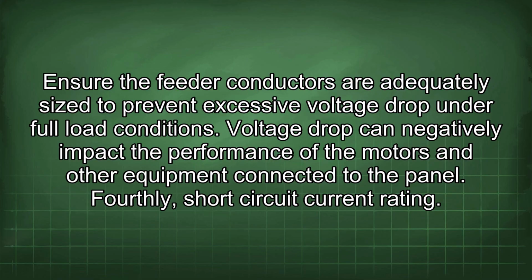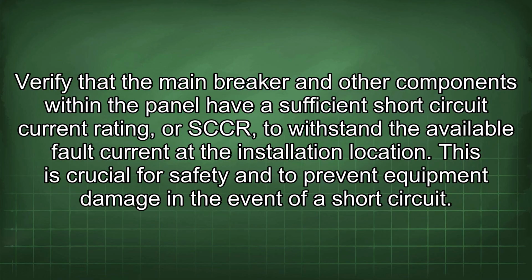Fourthly, short circuit current rating. Verify that the main breaker and other components within the panel have a sufficient short circuit current rating, or SCCR, to withstand the available fault current at the installation location. This is crucial for safety and to prevent equipment damage in the event of a short circuit.